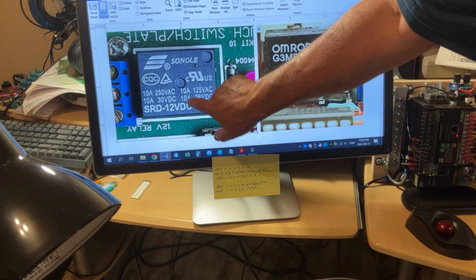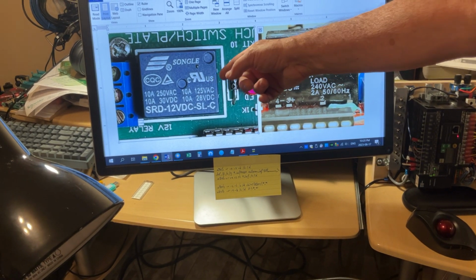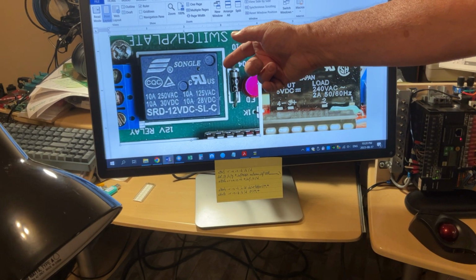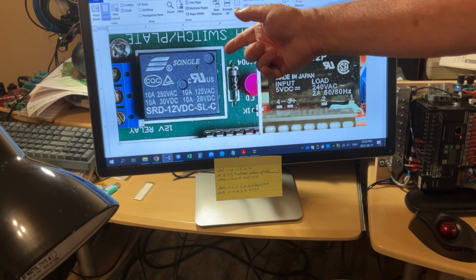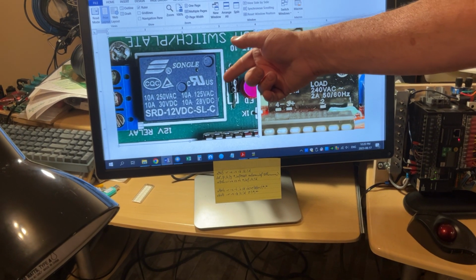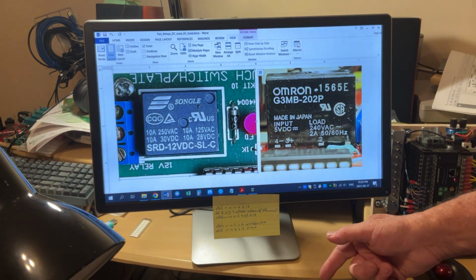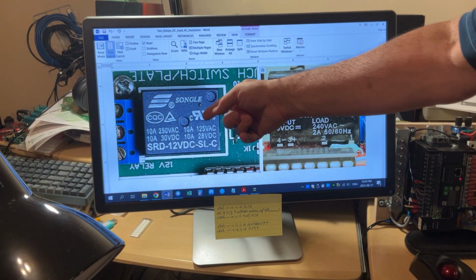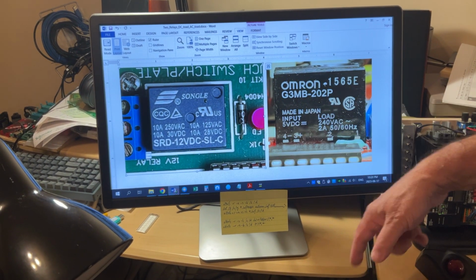this is the maximum amperage the relay can stand. So never use the relay for the maximum amperage. Use a common sense rule, no more than half, okay? So if it says 10 amps, don't use it for more than 5 amps.